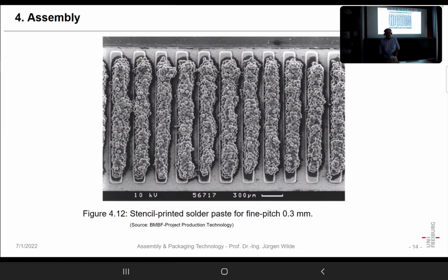We were aiming at, what's the trend in electronics, as we have seen in microelectronics: more IOs, higher frequency. If you want to have more IOs, you must have smaller pitch, because you do not want to have a device that is 1 square meter big. You cannot put that processor on your printed wiring board, so you need a small device. And having it smaller, you need smaller structures also for the interconnection.